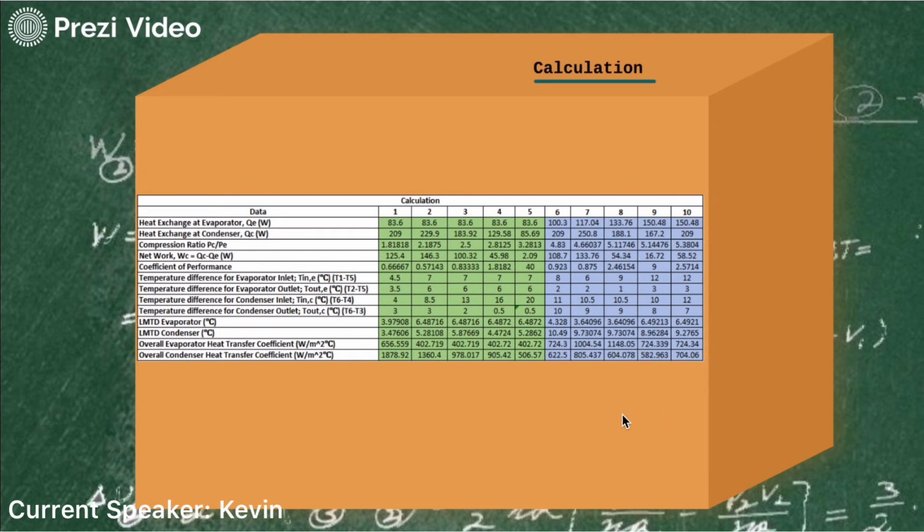These phenomena occur due to the increase of temperature on the condenser, consequently increasing the condenser pressure. The rise of pressure decreases the volumetric efficiency and reduces the specific volume of the refrigerant gas.